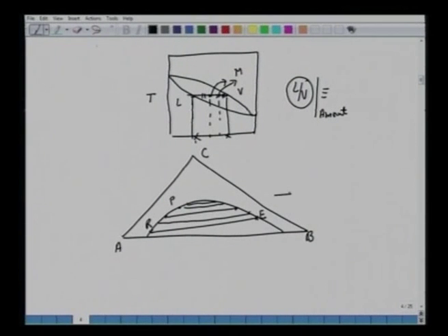If you take these projections and plot just like Y versus X, we are going from this triangular diagram to a Cartesian coordinate system with Y and X. Call the extract weight fraction Y and the raffinate X, plot Y versus X with a 45-degree line, and you will expect a curve like this.